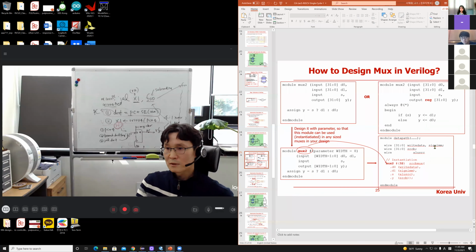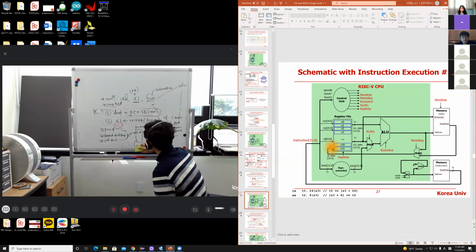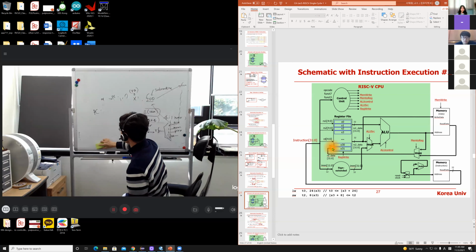let's go to here. Okay, this one is simple, right? This multiplexer, right? That is your question. If you have a conflict, then there should be some hardware component, right? You cannot connect the ALU output without a multiplexer. Think about that. How would you connect the ALU output to this input, the register file data? And this connection, data output to here. That is not possible to connect, right?